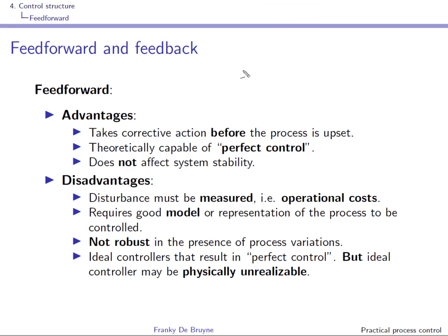We will see later that the feedforward action can be implemented as follows. So it is the dynamics of the disturbance times the inverse of the dynamics of the process, and it's acting on the disturbance variable.